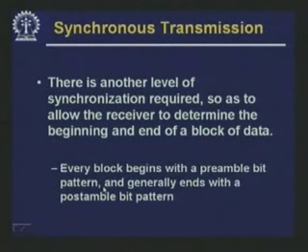Now, apart from this synchronization of clock for the bit, where does the bit start and end, or especially the middle, apart from that you require another level of synchronization, so as to allow the receiver to determine the beginning and end of a block of data.